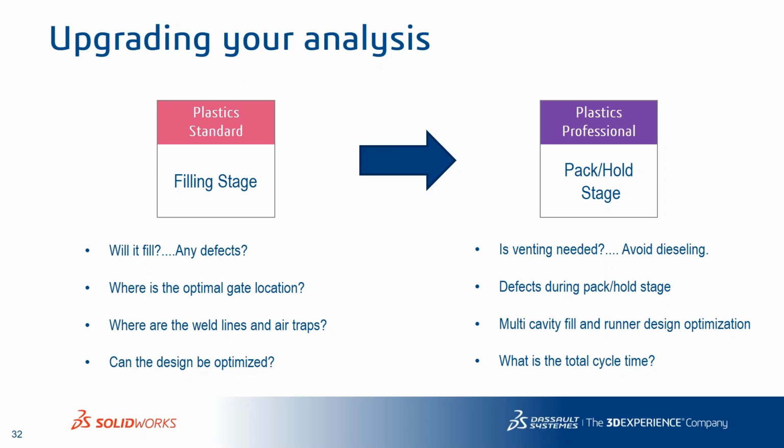And obviously the big question here, what is the total cycle time? We need to include everything. We need to include the filling, the packing, the holding, the freezing, all of that, to really understand how much time it's going to take for that part to eject out of that injection molding machine.